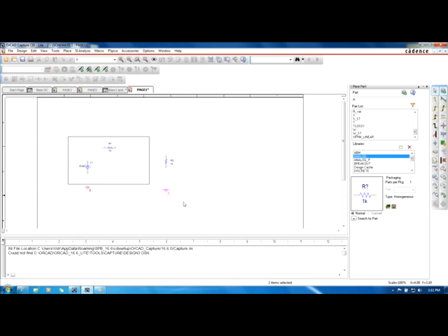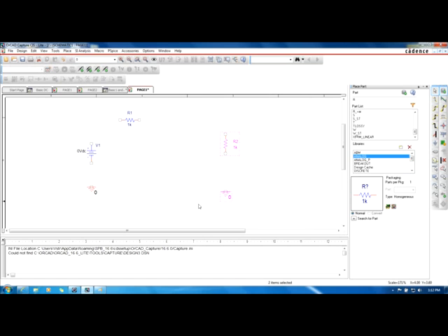Okay, now let's zoom in on this a little bit. Let's move this over here. By the way, I zoomed by doing, when I have nothing selected, a right mouse click like that, and drag it, and then let go, and that zooms in on it. So you can zoom in on just this voltage source right here with the resistor. Anyway, it seems to kind of remember where you zoomed from too a little bit.